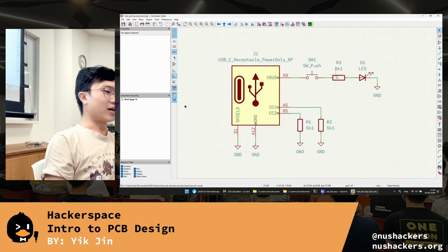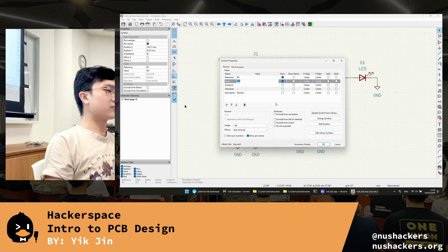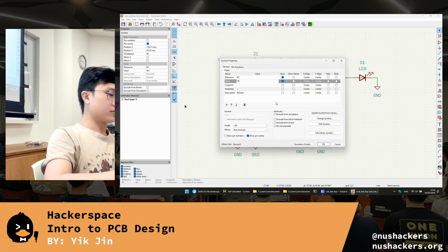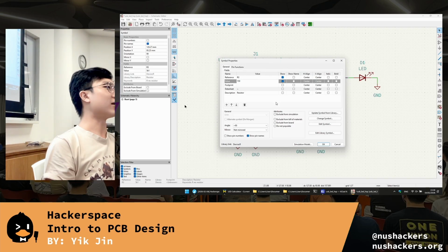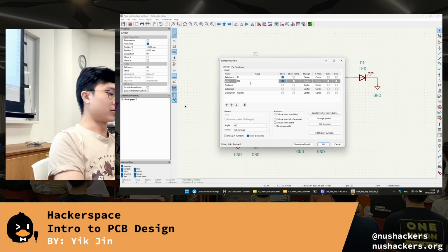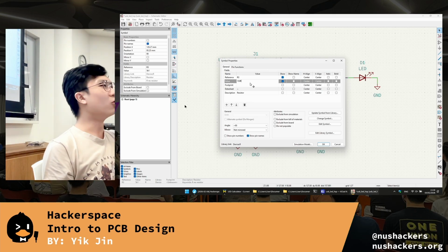Yes, so 150, right? So I go over here, double click on it. 150. Usually, for values without an SI prefix, you don't type ohms for resistors. You type R. Why R? Because the ohm symbol is not ASCII. So sometimes it might cause problems.